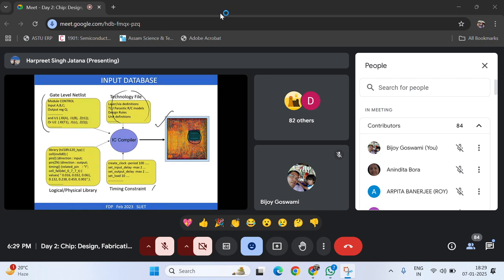Placement of this becomes an important thing because this processor will be interacting with various other blocks. Where it has frequent interaction with some memory or any other IO, you have to place it in such a manner that the overall functionality is met. That is a part of the floor plan. This is just to explain one example. There may be some 3-4 such blocks, and so the placement of those blocks is very important. That's why the floor plan has to be done very carefully.